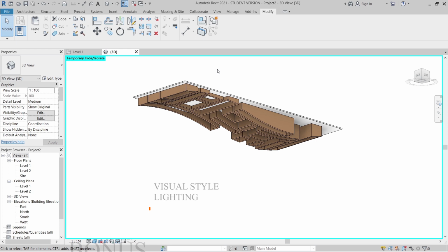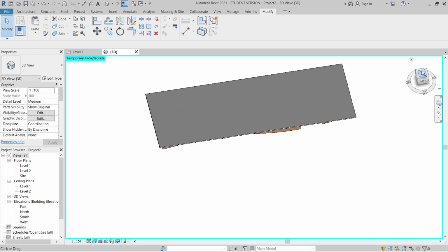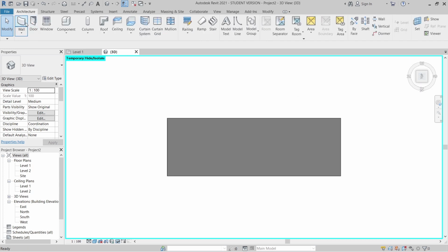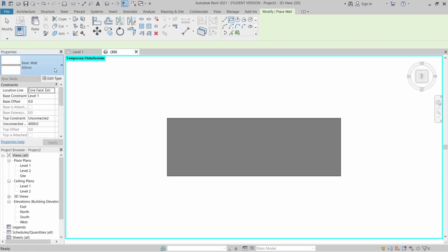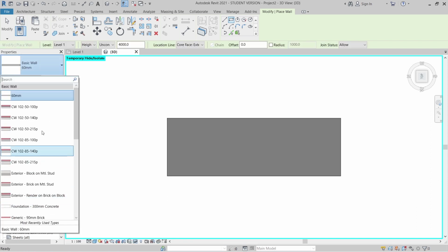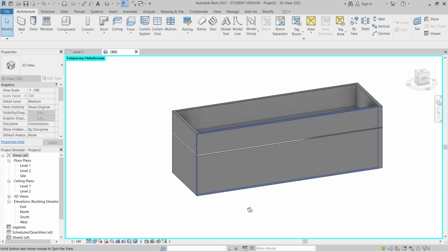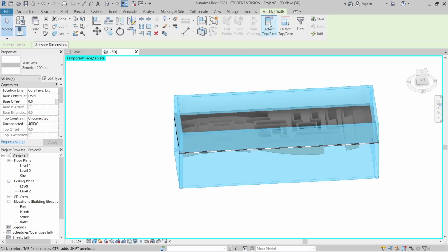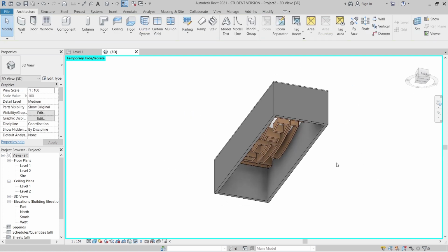This is the banners for our tutorial. Then I will start from creating our wall first. Start from top again. Architecture tab, wall. Make it for 4 meters. And start with rectangle. Just start it like this. Okay, we need to change first. Hit escape. Let's see if we can attach to top or not. Okay, can. As you can see here.